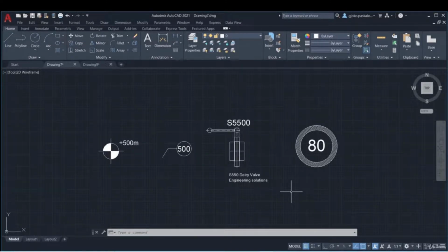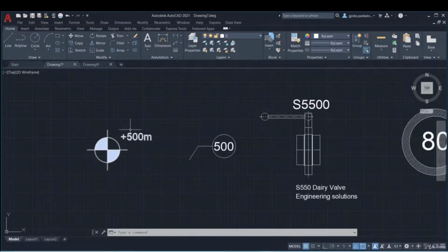Basically, attributes are taglines that are attached to a defined block. So the taglines will dynamically or statically input data to the block. For example, I have this drawing here. We have the block, and let's say this block represents elevation of a house. The second one represents some specification of, let's say, an element of the house. And actually the attributes are the text inputs.